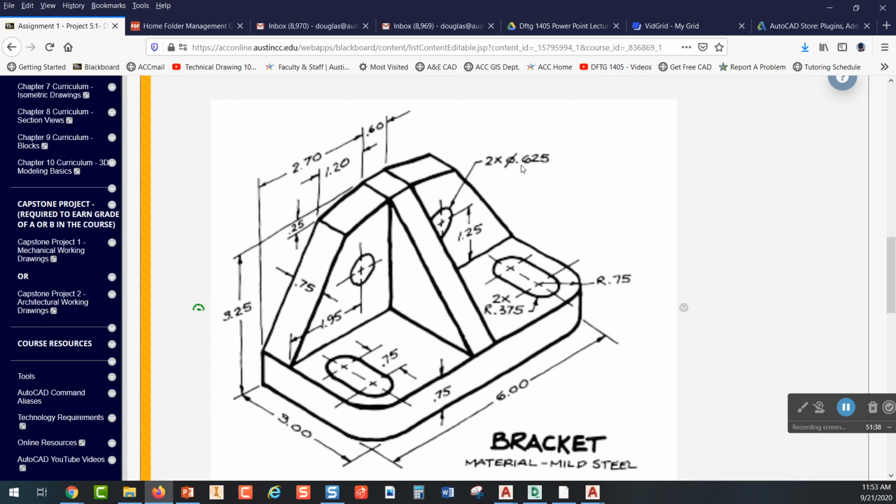And when you highlight it, you need to check and think about, did you write 2x? Did you go to 3 decimal places? Did you put the R in there and go to 2 decimal places here? If so, you would highlight that. And so what I recommend doing is highlight this as you put those dimensions on the AutoCAD drawing. Then after you have your PDF, compare the PDF to this sketch and highlight it again. Just make sure that you've got everything on there and it's all the same precision.